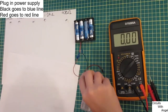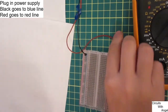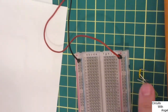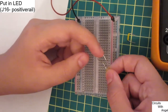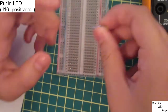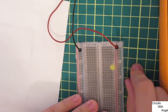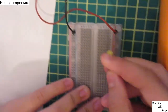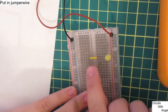Now we get building our circuit. First, we take our LED. Well, not exactly. First, we have to plug in our power supply. Now remember, black goes to blue and red goes to red. The long leg goes to the positive rail, to an empty row. We take our jumper wire next, connecting the LED's row to another empty row across it. Make sure the jumper wire is connected to the LED's leg, or else this circuit will not work.